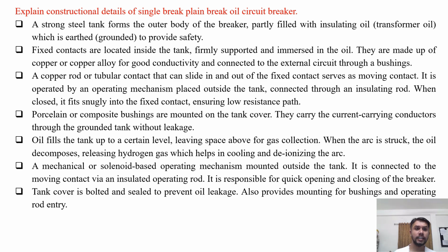Explain constructional details of single break, plain break oil circuit breaker. In this, a strong steel tank forms the outer body of the breaker and it is partly filled with the insulating oil, which is known as the transformer oil. The tank is earthed or grounded to provide safety. Whenever we touch the outer body of the tank, we should not get a shock. Fixed contacts are located inside the tank, firmly supported and immersed in the oil.